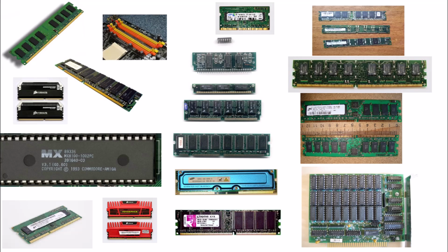Flash EPROM memory. In this type of memory usually single bytes can't be erased or programmed. It is possible to erase and program by blocks of memory or as a whole. Flash memories can withstand from 100 to 10,000 erasing and programming cycles.